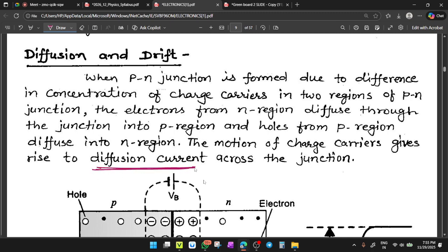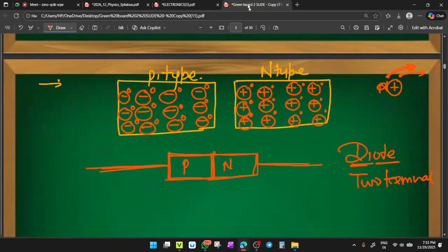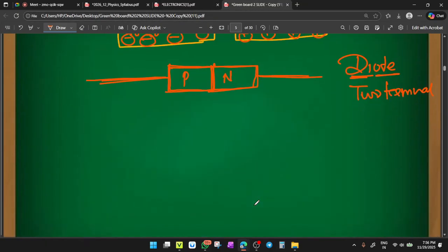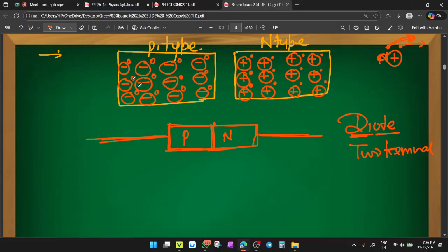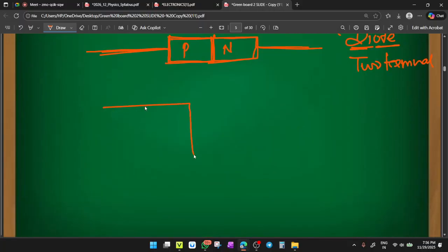See, there are two currents. First, it is the diffusion current. Try to understand when the diffusion current is established. Like you just join the junction. This is the first time you have joined the junction. Just as you join this P layer with the N layer, what is happening there? You can see that a P-type material is there, with positive holes over negative immobile ions.